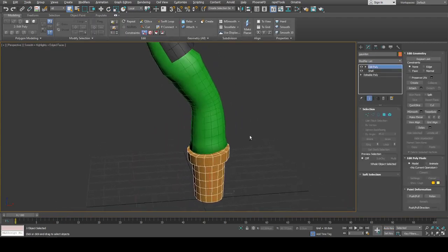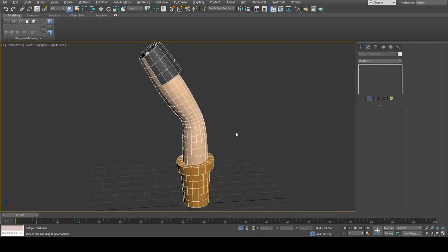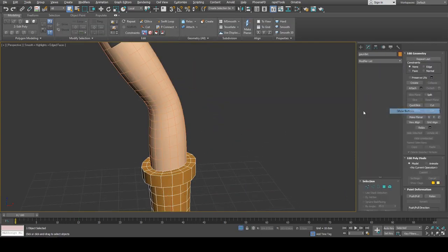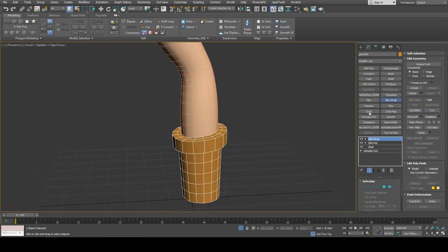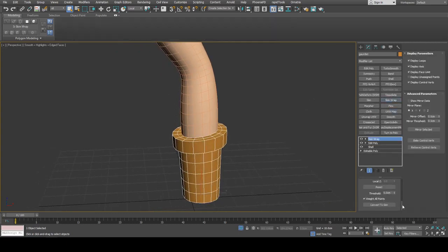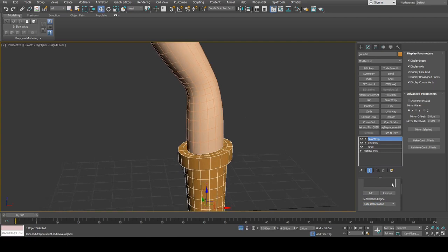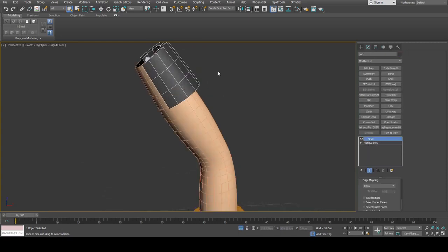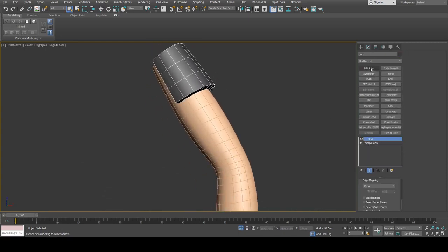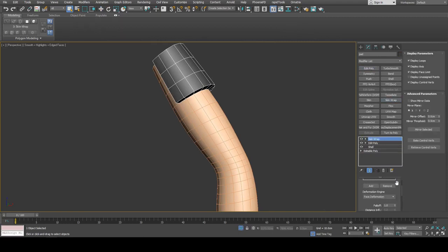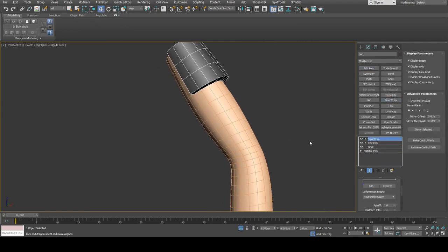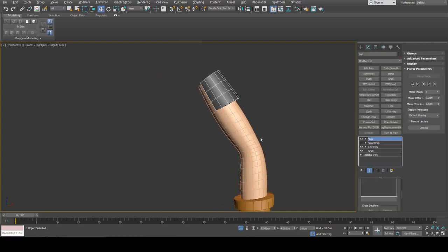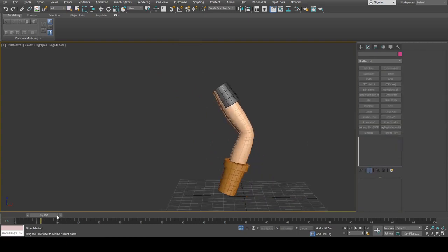All right, what I'm going to do is just to use skin wrap on this. Reactivate my modifier buttons here. All right, skin wrap. Weight all points. Switch this to face, and then select the arm. All right, afterwards, convert to skin. Do the same for the pad right here. And convert to skin. All right, so now the gauntlet and the shoulder pad are following along.